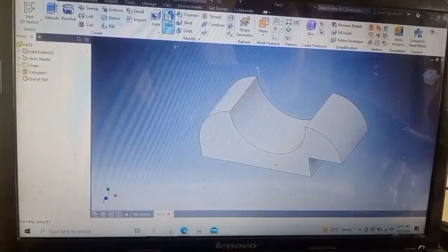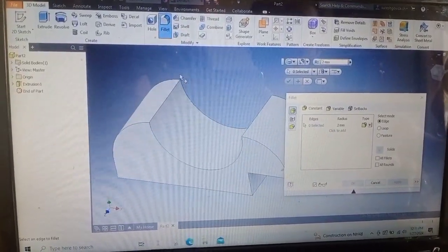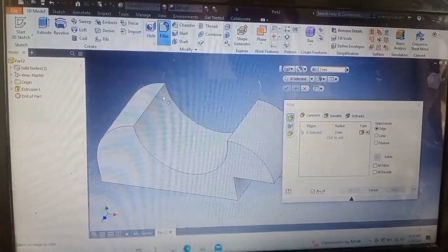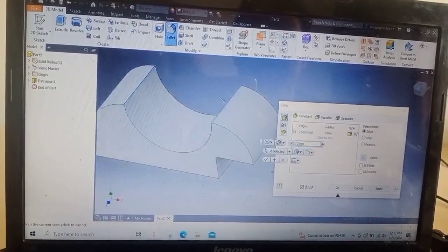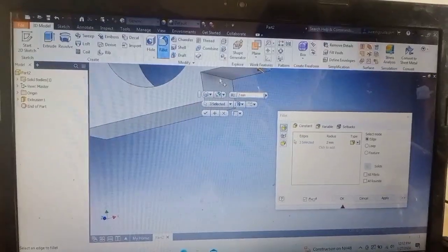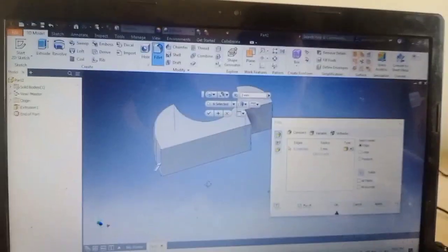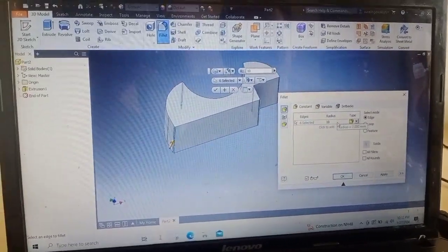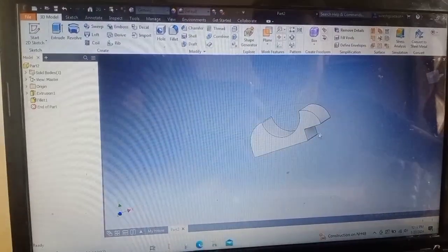Just if I want to make them round, I use a fillet command. Anyway, I give all those details in 3D video course, but right now I'm just explaining this one just to give you some insight into that. I'm selecting that edge, this one, this one, this one. I'm holding, okay, this one. So I selected all the sharp edges, and here you are seeing radius as 2. I change it to 10. You can see radius is created.